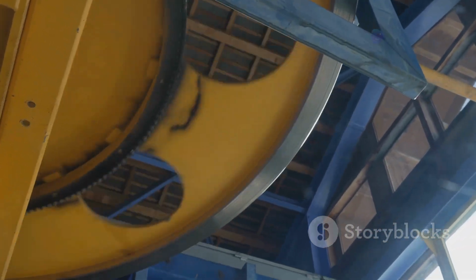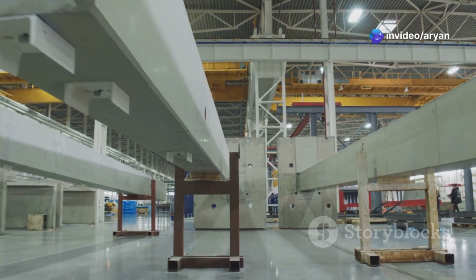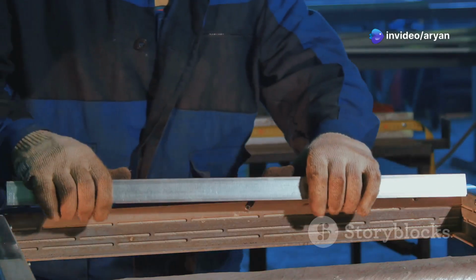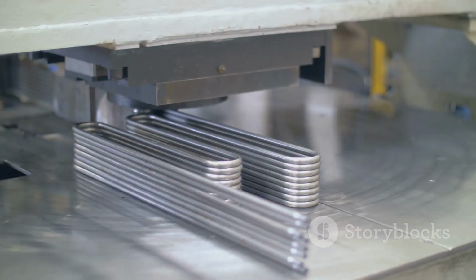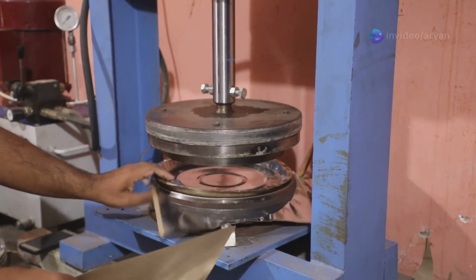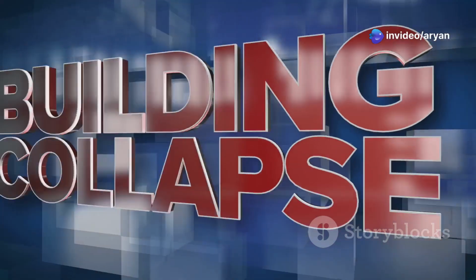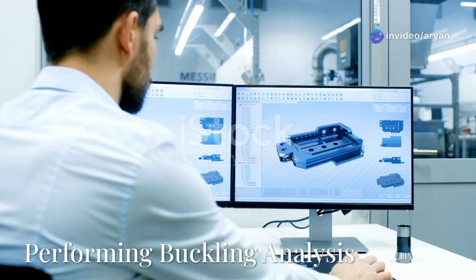Another advanced technique is buckling analysis, which is essential for beams under compressive loads. When a beam experiences compression, it can fail not by direct material failure but through buckling, where it deforms drastically out of shape. Buckling occurs when the compressive load exceeds a critical threshold, causing the beam to fail due to instability rather than material failure.